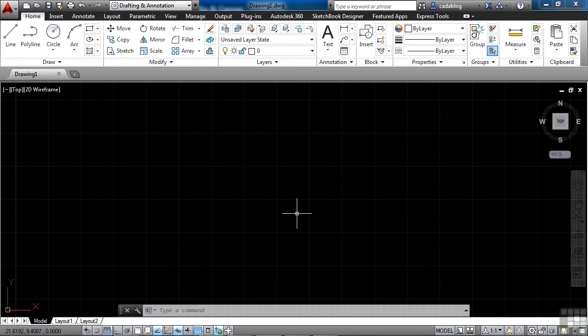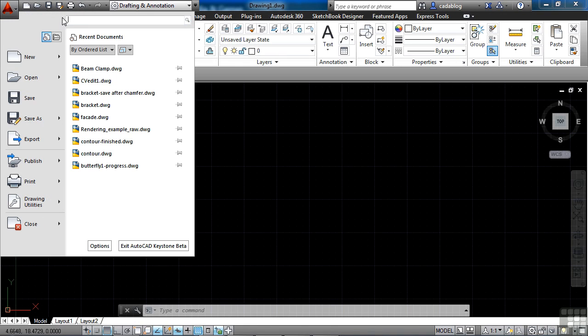Now, AutoCAD can do a lot of search for you right within the command line, and we'll talk about the command line later on. If you like to use the ribbon more often because you're more comfortable that way and you can't find a command, just go up to the application menu, and in this top bar right here, that's a flashing cursor, and it's there by default when you start the application menu. Well, there you can do a search for commands.